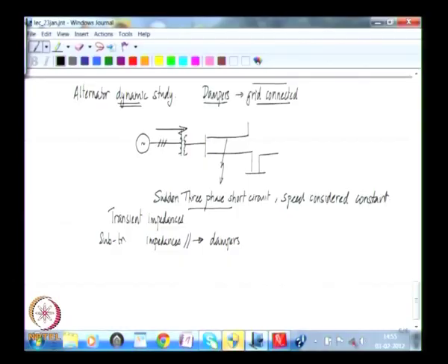In order to understand all this, what we will now do is proceed by studying the 3-phase short circuit behavior of the alternator, starting from the dynamic equations of the machine, including the representation of dampers. So we will look at one damper circuit on the D axis and one on the Q axis,